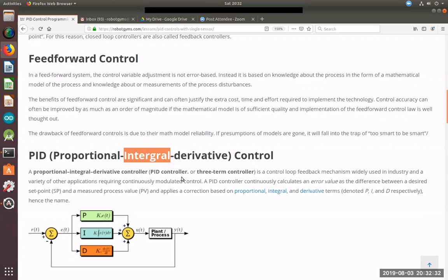For example, another thing we compensate for is if the robot goes up hills: instead of the error decreasing, the error increases because you roll back. The trend is totally different. That means both the integral and the derivative will ask you to apply more power, right? So basically PID control is these 3 terms. Look at your current condition, that's proportional. Look at your history, that's integral. Look at the future, that's derivative.